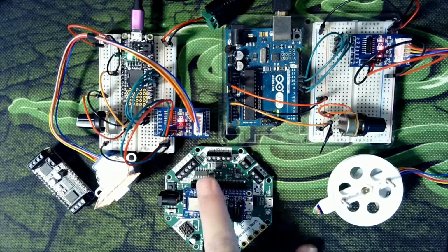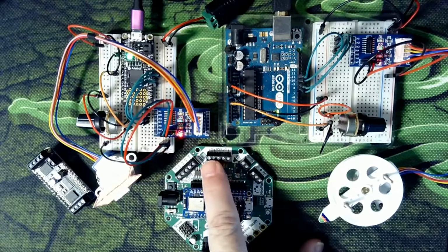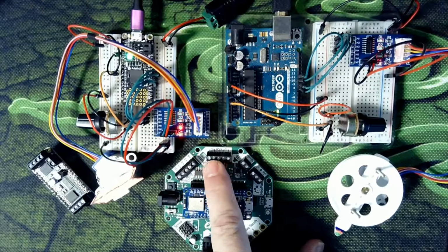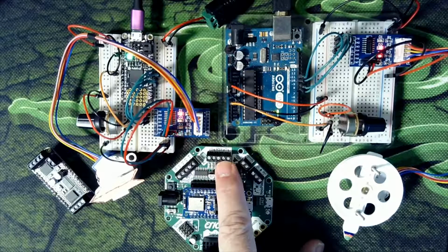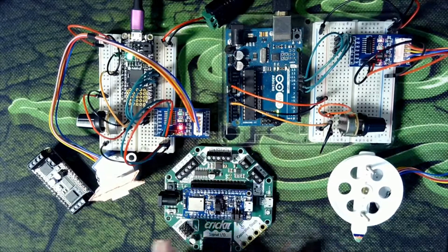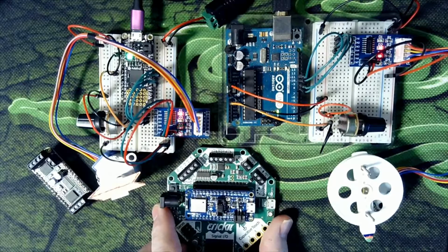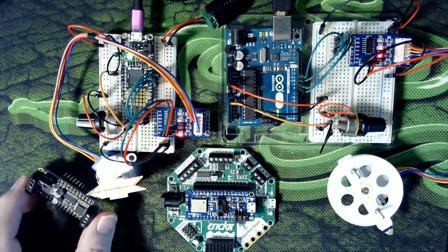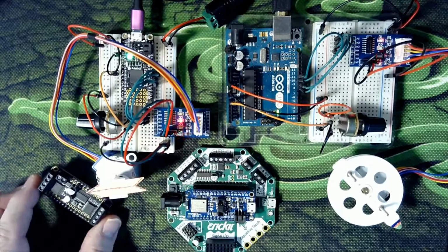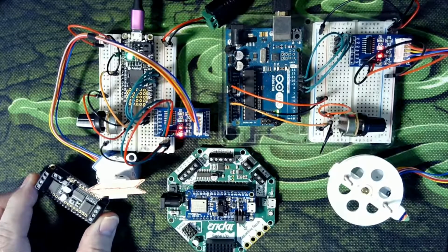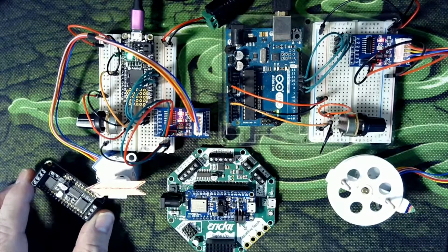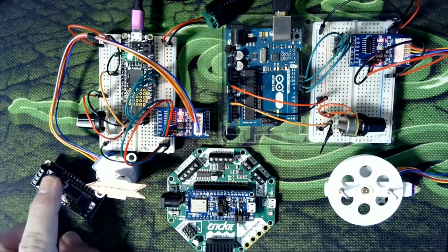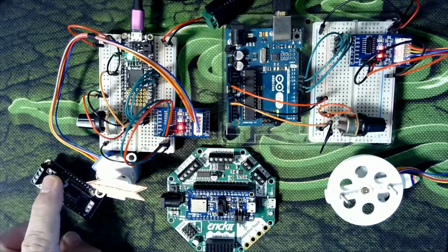On these pins over here, it has motor connections where you can connect either DC motors or a stepper motor. So you have the ability to run it from something like this, which is referred to as a daughter board. Then I have this other one here, which is another Feather board. This is actually a motor driver board. It can drive individual DC motors, up to 4 of them, or it can drive 2 stepper motors, one connected to each end. And again, it brings its power in from a separate source over here.